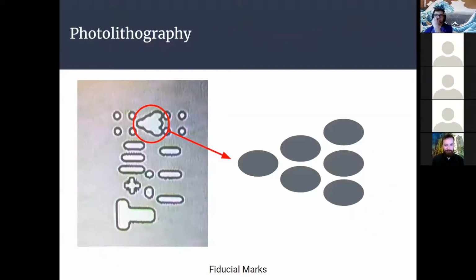And so this is a practical example from the summer lab. We have this little shape up here that we call the rocket ship. Because the photomask that we had wasn't perfect, rather than getting these separate ovals like this that were actually on the photomask, we were getting images like this where they all kind of blended together. In the end that doesn't really matter, because these are called fiducials, and they're essentially just alignment marks, so that when you're applying a second layer of photoresist, you know where to line it up on your mask, to make sure when you deposit metal onto it, the metal is going on the right places.